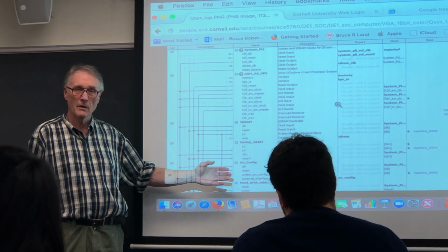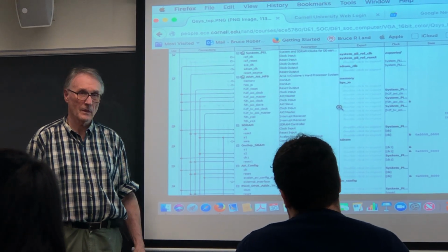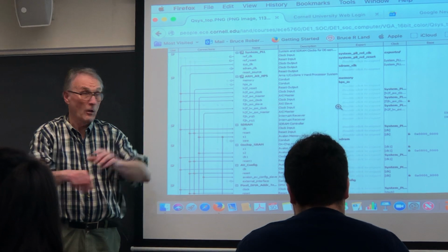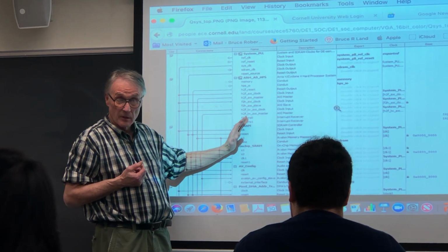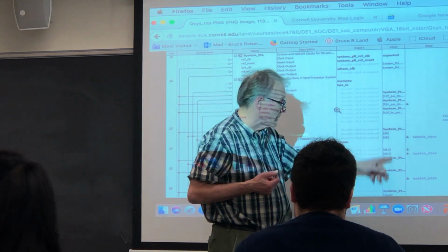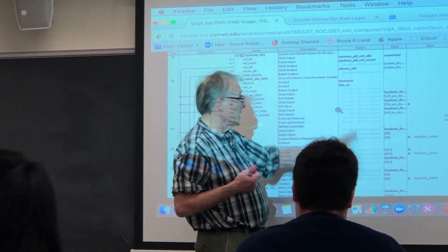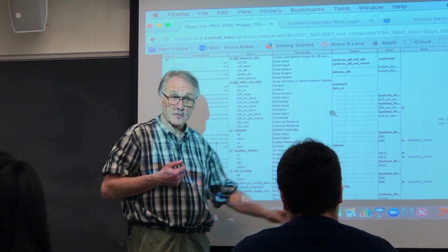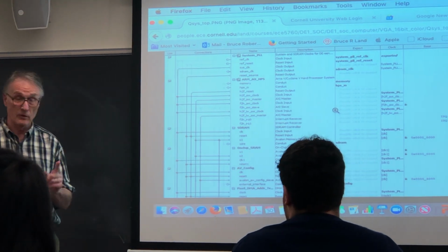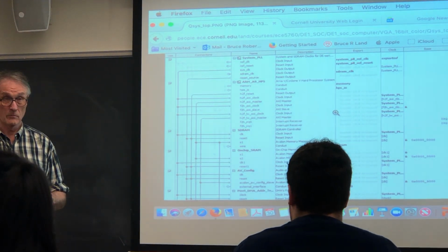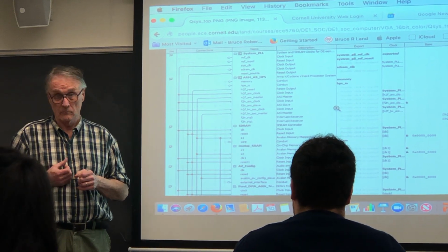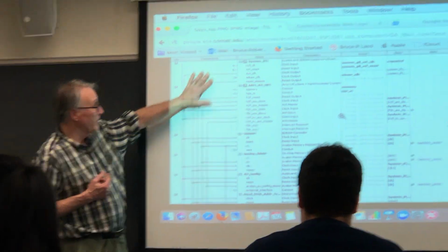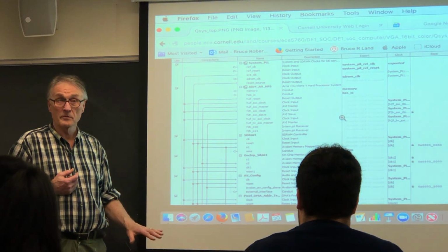Well, it matters for stuff like the integrator code you gave us, which seems to be assuming it resets when it goes low. That is in the Verilog code. That is not on the Qsys bus. So the signals that come in here through the exported signals have a polarity that you control, and you have to worry about that. But this is all completely hidden from you in terms of Verilog.